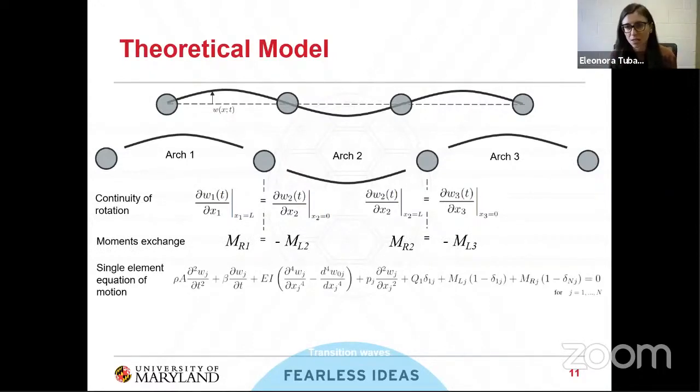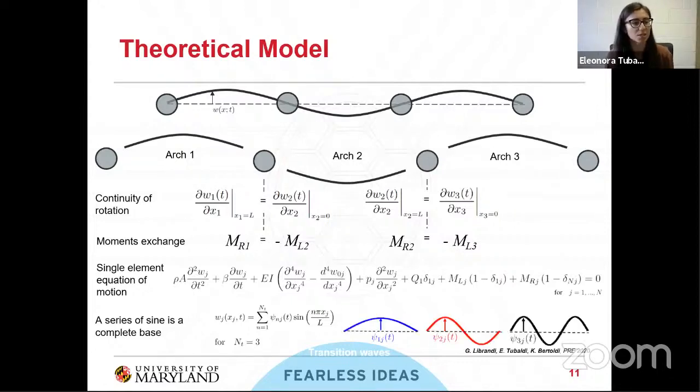And as you see, it is a PDE, a partial differential equation, but by using a series of sine functions, which is a complete basis for the system, we can stop at considering 3 modes for replicating our dynamic response. In this way, we can easily integrate our system and find the temporal response.